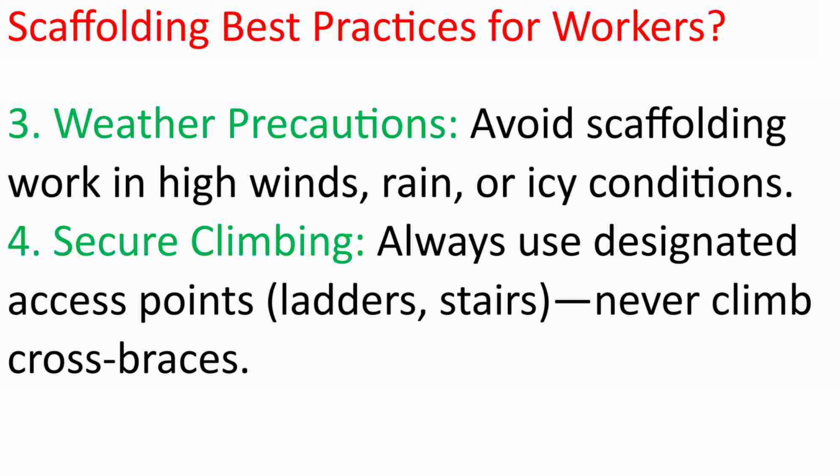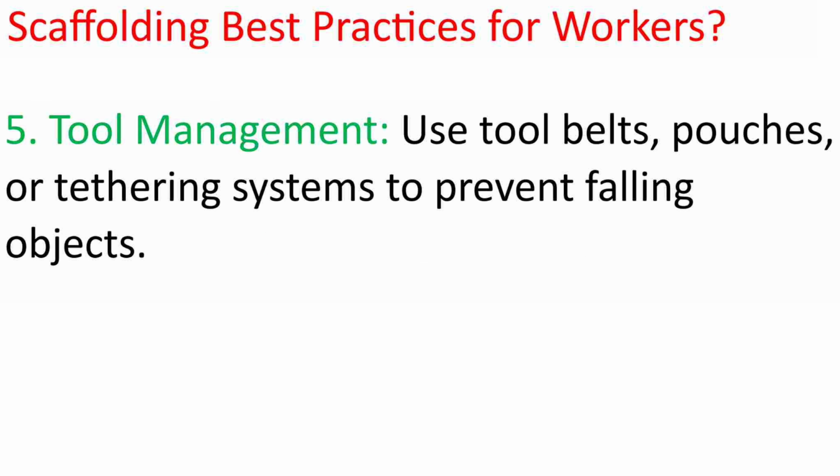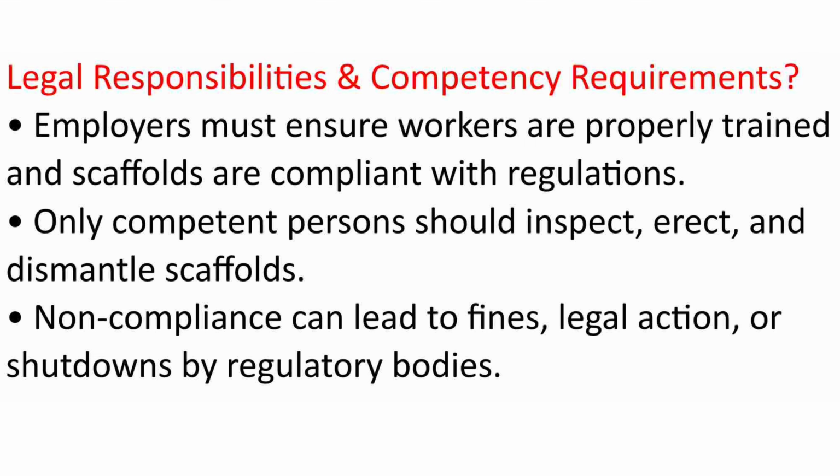4. Secure climbing. Always use designated access points, ladders, stairs. Never climb cross braces. 5. Tool management. Use tool belts, pouches, or tethering systems to prevent falling objects.